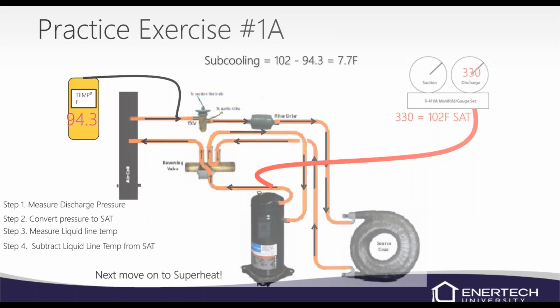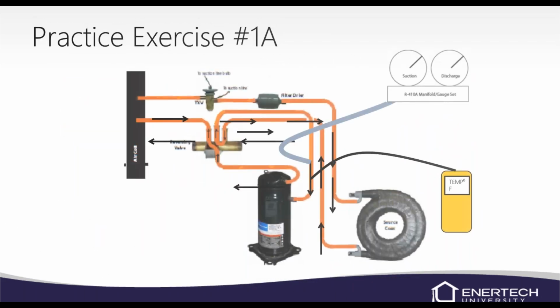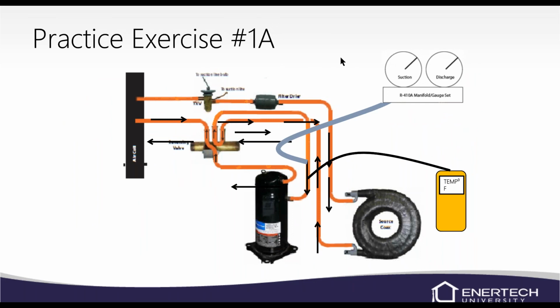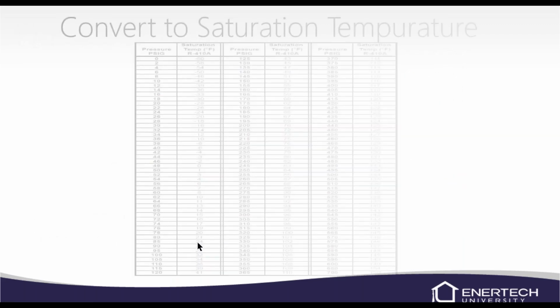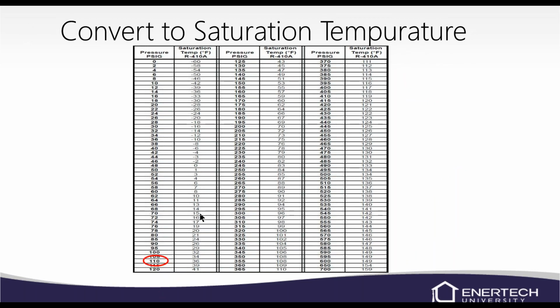Again, superheat is not going to change from heating to cooling. Right there where the bulb is located, measure our suction pressure of 110. And we'll look at our saturation temperature at 110 psi. So 110 is equal to 36 degrees.